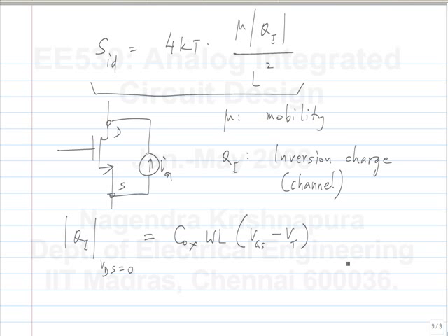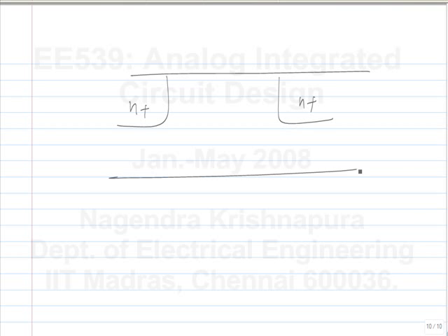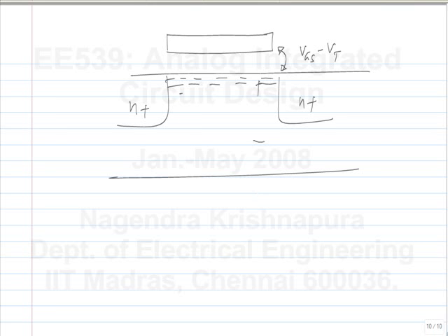When a MOSFET has an inversion layer, this capacitor has VGS minus VT across it, and the threshold voltage is dropped between the channel and the bulk. In fact, that's the definition of threshold voltage: the voltage at which the channel starts forming.